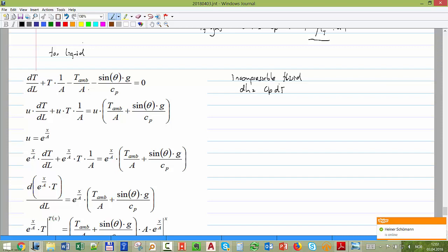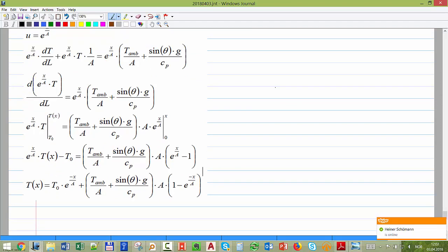You get to that equation that you are using. We have different developments for gas and for multiphase flow, but we don't have time to cover all of them. Just to make you aware, liquid is really the only one where we can have an explicit expression. For gas, it becomes implicit, and we have to solve the equation in an iterative manner.